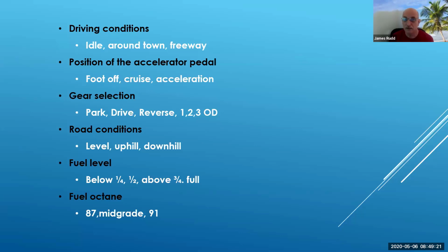Now on some of the older cars, if the timing is not set correct, we can have some of that lag too. But you can find that with a vacuum gauge fairly well, and it will show kind of a low performance on the vacuum. But if you've got an actual dead drop off, like you feel the car shakes as you go up, you definitely have some kind of ignition breakdown going on. All right, moving on. Good question.